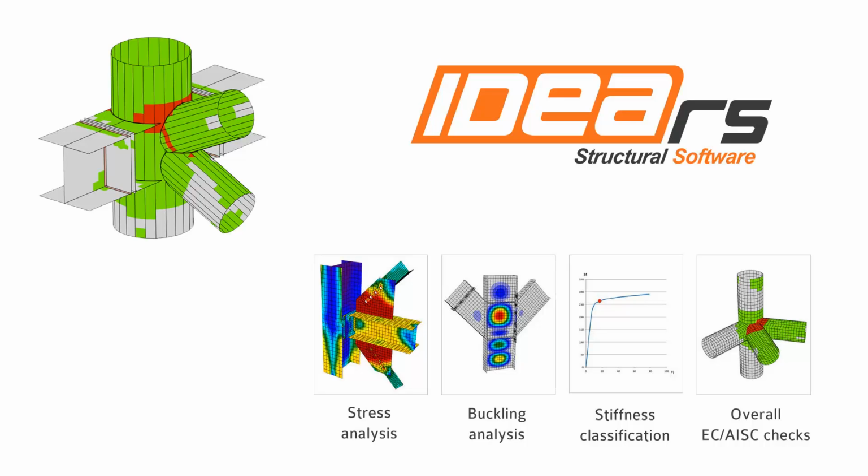In this video we would like to show you not only how we design a connection with Idea Statica, but the workflow that we can follow if we want to combine our main structural analysis software that is used for the global analysis of the structure. Of course, a steel connection can be very easily created within Idea Statica, but still it is very useful to import the connection from the main structural analysis software because we can also import automatically all the forces that are applied to the node. That allows us to save time, of course, and avoid also any typo mistakes when the input of loads is done manually.